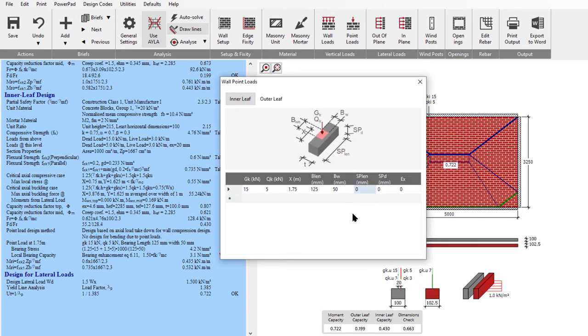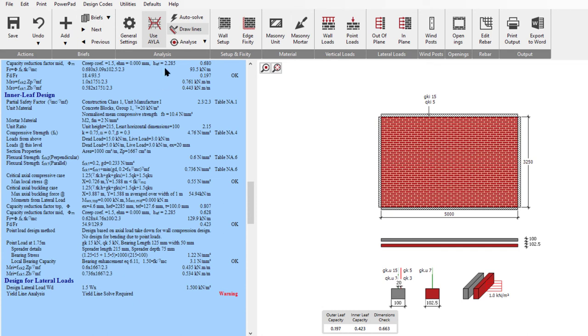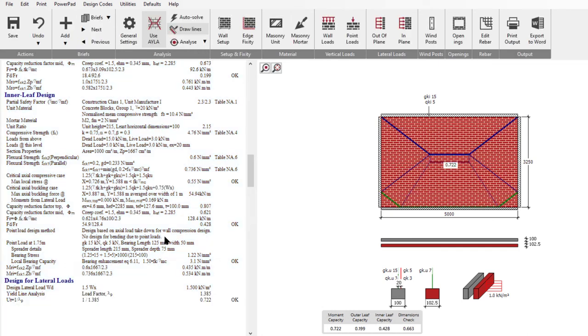Well, we can put a concrete pad in, so make it 440 by 250, or I'm quite inclined to make it 215 by 75 engineering brick, see how that goes, and analyze. And in our case, an engineering brick or 2 engineering bricks is easier to put in than casting in a wee bearing pad. So that's a single point load. We can put another one in. So that's our point loads.